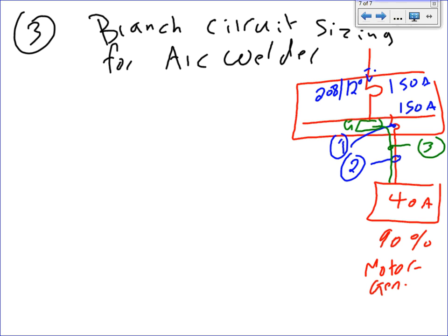To help me with this, guys, I want you to go to the same article almost, 630.11(A). If you guys read through 630.11(A), it will tell you how to size the conductor for the welder. And for the overcurrent protection device, which one are we sizing? Let's start with number 1, the overcurrent protection device.